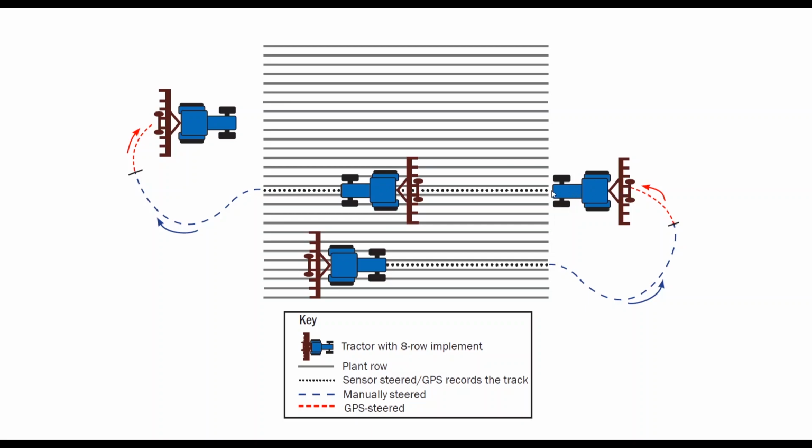Once it has steered and maintains a GPS guidance line, or steers to the GPS guidance line with minimal deviation parallel to the line, it'll then automatically switch back to row guidance. So it'll automatically GPS steer you into the next pass. Once it's on the pass, it'll switch to row sensors, and then it'll proceed to guide with row sensors. Same process as before. When you disengage again, it'll then create another new AB line and calculate X distance over for the next pass.